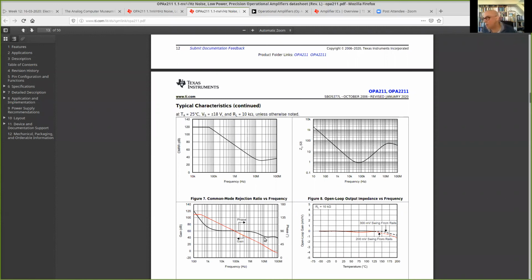But that is a rule of thumb, and it's really difficult. If you have a capacitive load on this amplifier, it can be very important where this capacitor is. If I put a capacitive load here, so this is my load characteristic, then here I would have resonance. If I put the capacitive load here, a very small capacitor, so high impedance, then you see it is not influencing anything.